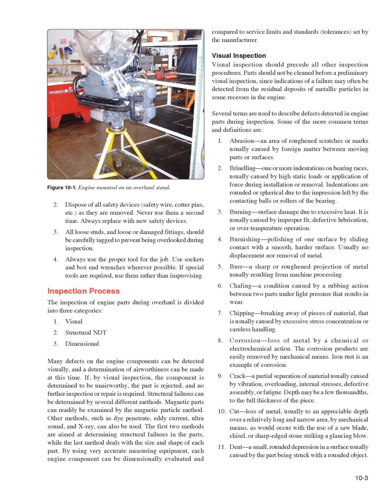3. All loose studs, and loose or damaged fittings, should be carefully tagged to prevent being overlooked during inspection. 4. Always use the proper tool for the job. Use sockets and box end wrenches wherever possible. If special tools are required, use them rather than improvising.